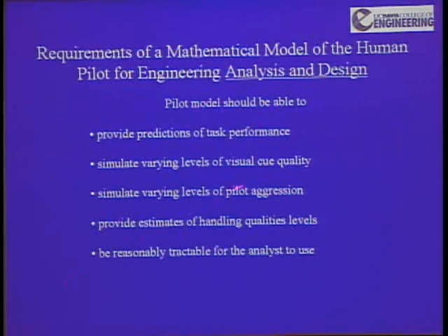So some of the work I've been doing now is using pilot models to analyze and design control systems. And what should a real pilot model be able to do? Well, it should be able to provide predictions of task performance that an actual pilot would generate in a given task with a given airplane. It should be able to simulate varying levels of visual cue quality, varying levels of pilot aggression. How hard is the pilot working? Provide estimates of handling qualities, and the last one is be reasonably tractable. That is, an analyst can actually use it.